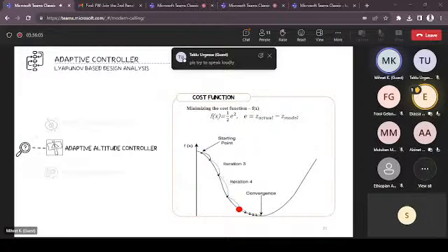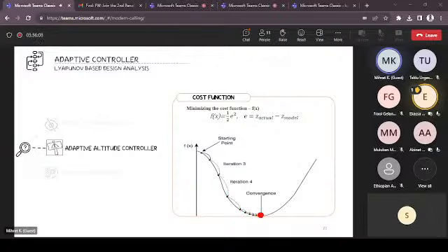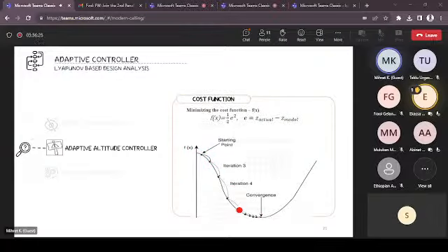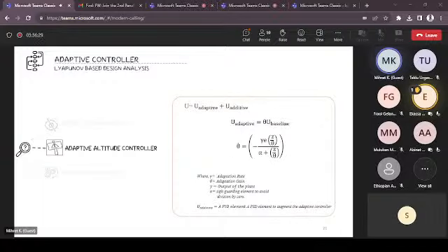So the fact that the reference model is nonlinear enables it to decode complex nonlinear behaviors the actual plant might exhibit. So the adaptive altitude loop is then built as a direct adaptive control scheme, which makes use of the modified MIT rule, and it's done by defining a parameter called theta, which acts as a variable gain, so that the developed baseline controller varies in terms of variable environments. Then the parameter adaptation law we see here is defined so that the defined cost function converges to zero.